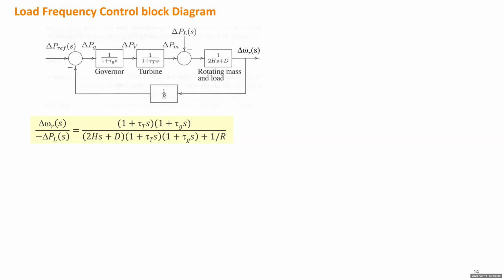On last Thursday, we talked about frequency regulations, and we introduced some very basic concepts of frequency deviations and the industry standards on what frequency is considered normal and what is considered abnormal. Following that, we gradually developed the models for each component of the load frequency control until we came up with this block diagram, so we can derive a frequency transfer function in the frequency domain.